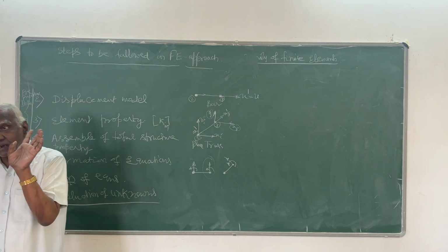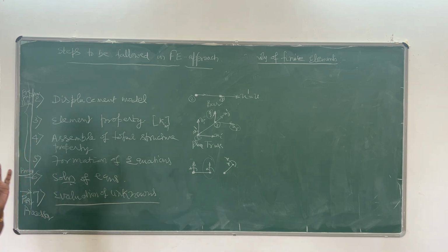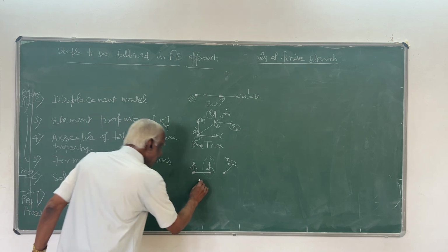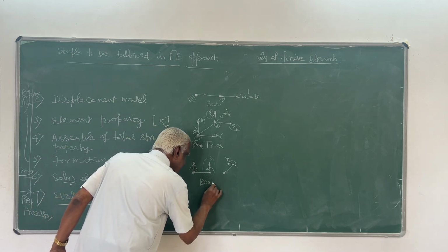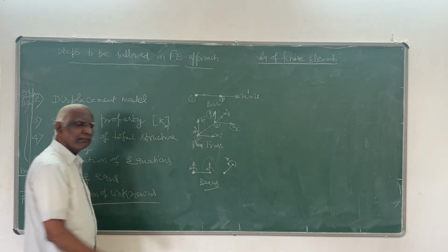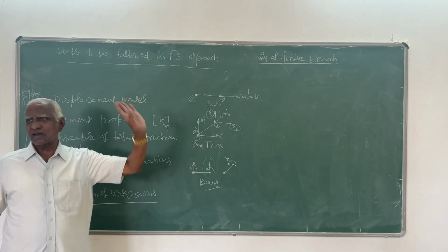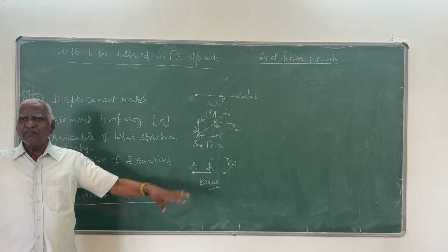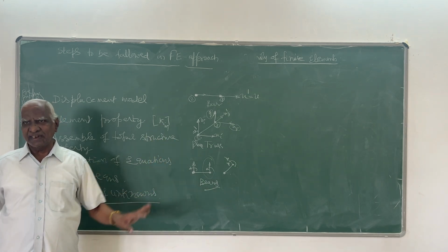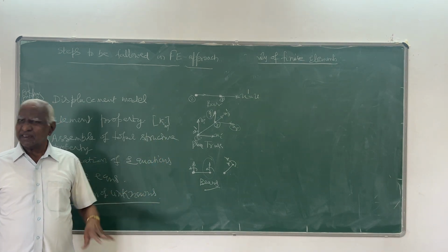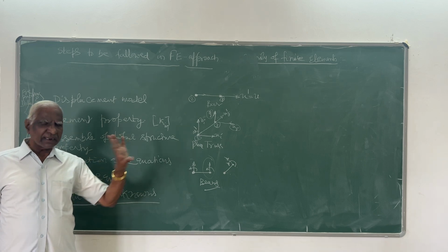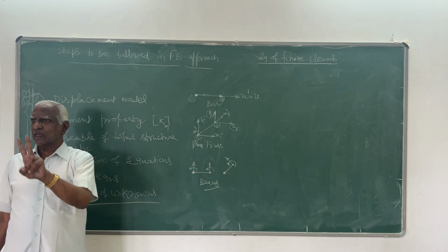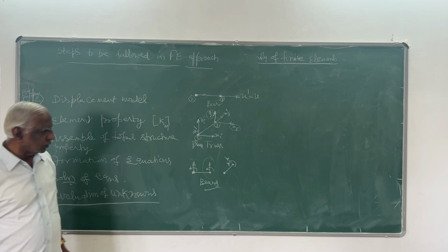3 will be there. That's the difference between beam and rigid plane frame. So this is in case of beams, inclined beam and of course the usual horizontal beam. Normally beams we define as the one wherein it is along a line. Even if it may be inclined, again we take only 2 degrees of freedom per node.